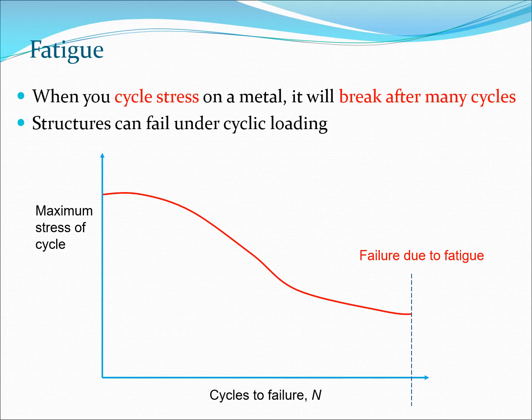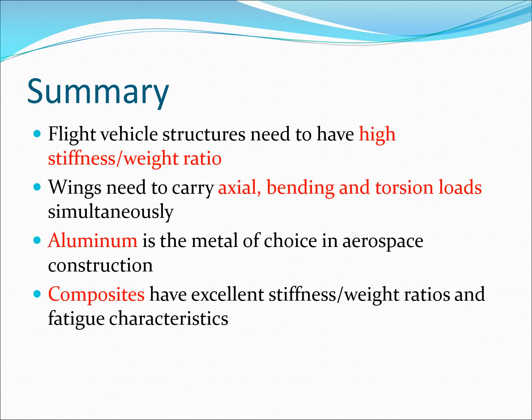So you need to know the cyclic and fatigue properties of the material also. It's not just enough to know the ultimate strength and so on from the static tests. So in most companies, they do a lot of fatigue testing of different materials to know where exactly they fail. There are various rules also regarding fatigue as far as certification is concerned.